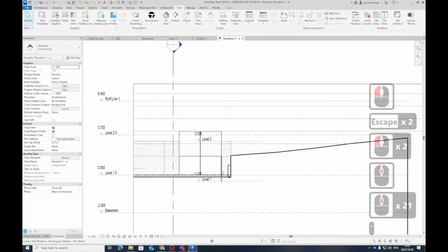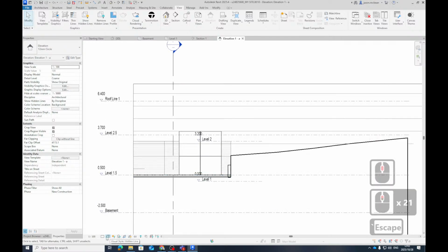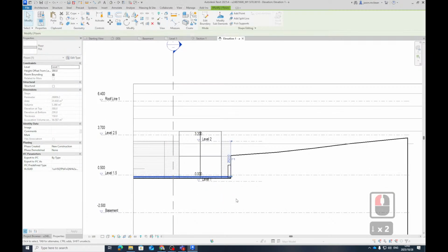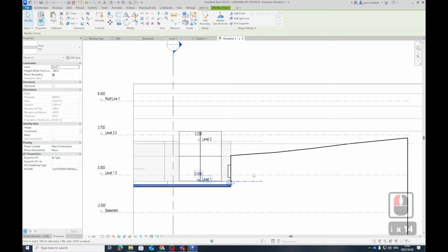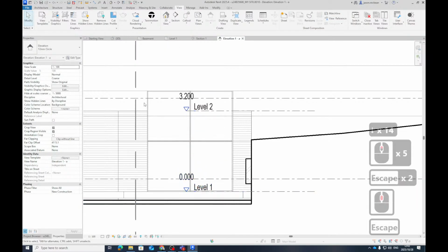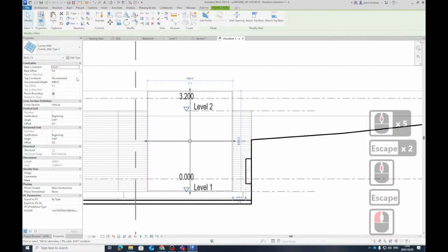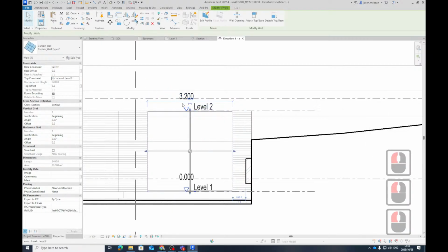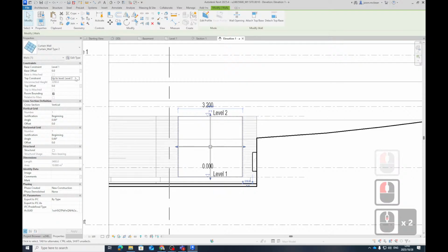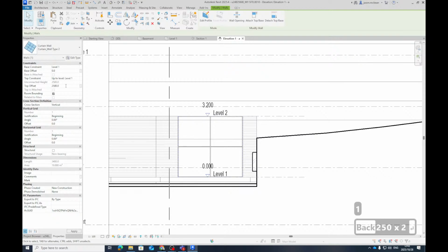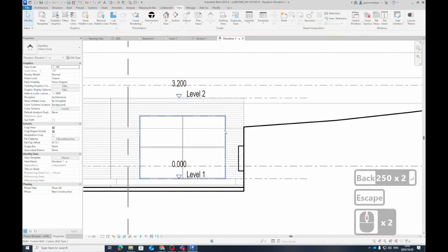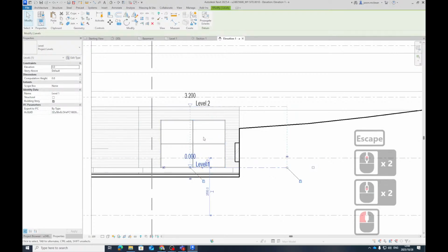That's going to focus, ignore the rest. Now, if you want to see through everything, let's make this guy a bit lower so we can see. Okay. Now, if I go and measure, this one must work from level 1 to level 2 maybe. See, level 2? But maybe not. I'm going to say level 1 because I know in level 1 the top offset must be, let's just say, let's make it 2500 for now. So, you see from there to there's 2500.